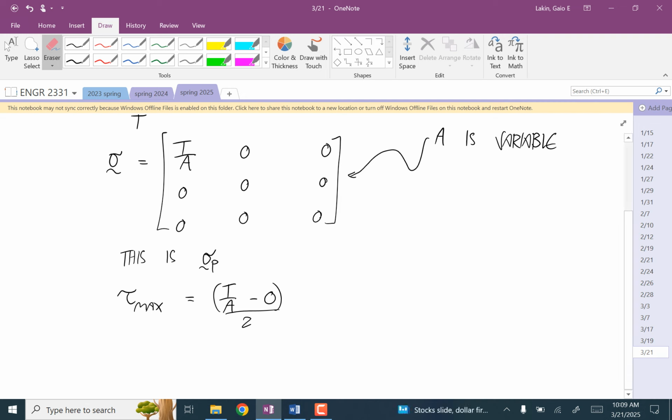For internal tension and compression, the stress doesn't depend on where you are in the cross section. It only depends potentially on where you are along the long axis of the beam. Oh, because it doesn't change throughout the length of the beam, right? It can, but not always. A lot of times it's piecewise constant. You'll just have finite changes where there are external horizontal loads applied.